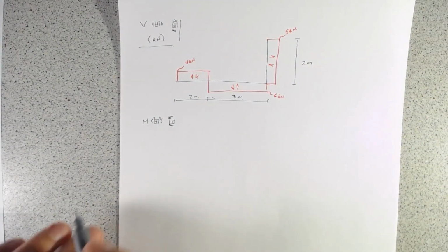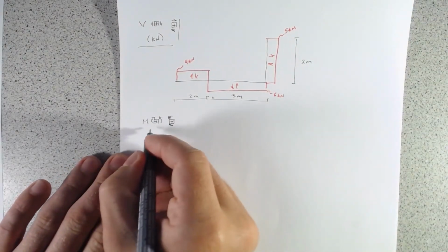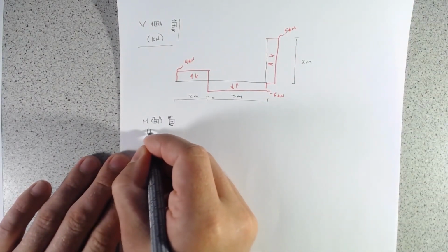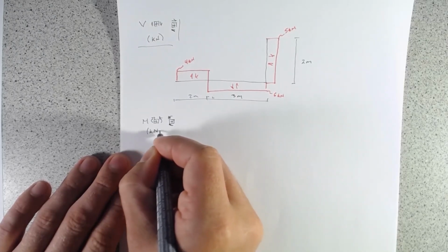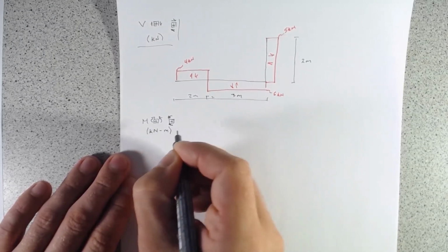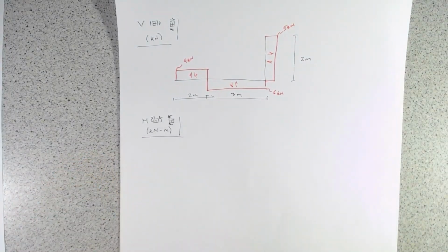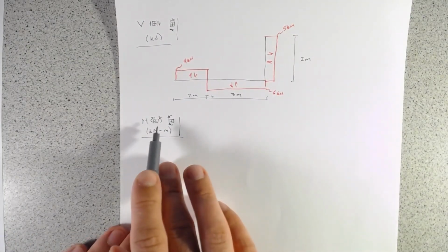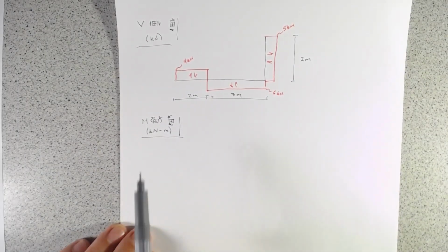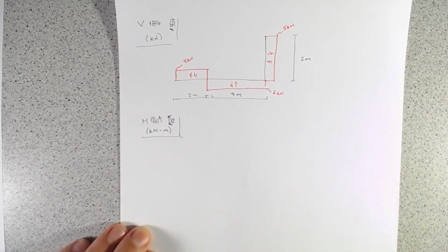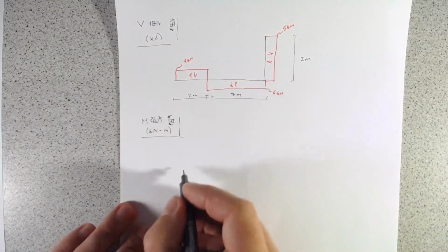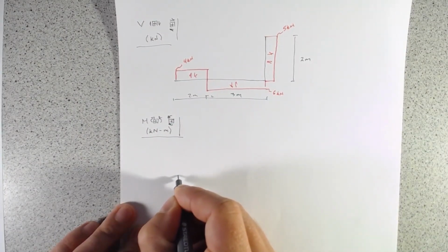Now which direction is positive and negative is more a sign convention aspect, but what will be an important bit of how we draw shear and moment diagrams is that we are going to plot them on the tension side. So if the portion of the element is in tension, well, that's where we will plot the diagram. And again, if you ever get confused, remember the tension side is where the tail of the arrow is. So drawing our little frame again.